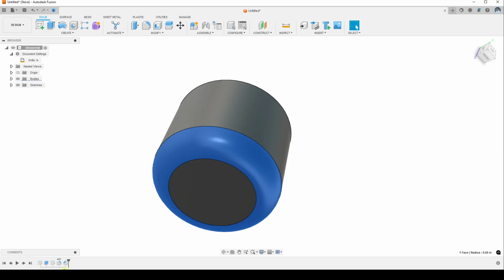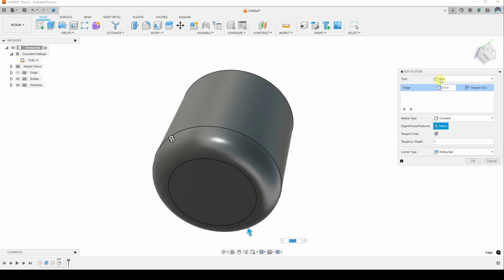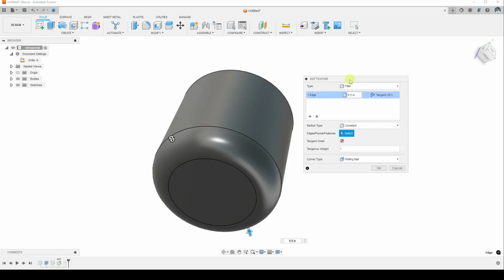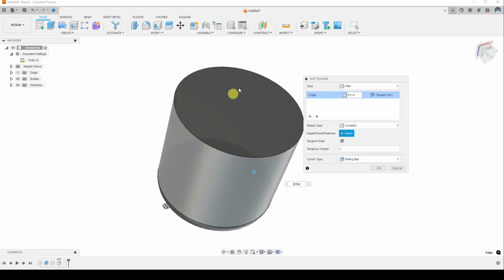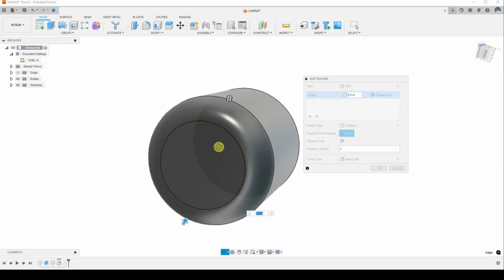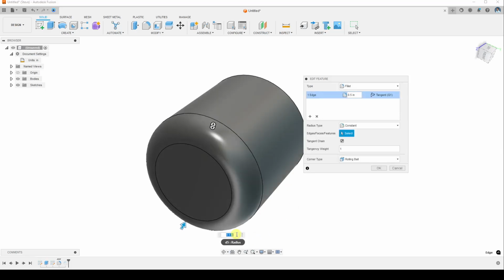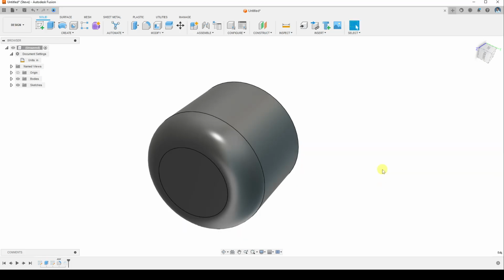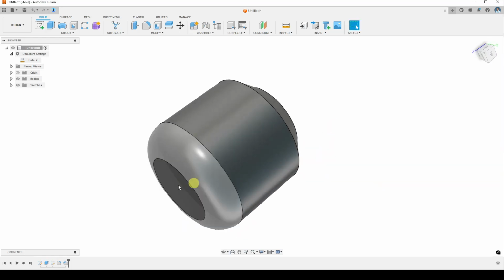And what I can actually do is go to the design history and double click on it. Yeah, I can double click on it and it brings up that feature again. It takes you back in time to that point. See, it took that chamfer away because I had made the chamfer afterwards. And I can make changes to it. I can make it 0.6. So you can make adjustments to those features based on what happened in the design history.